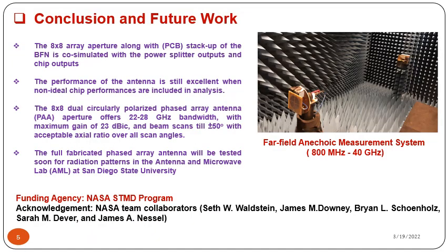So this 8x8 array aperture along with the PCB stack-up of the beamforming network is co-simulated with the power splitter outputs and chip outputs, and we found the performance of the antenna is still excellent when non-ideal chip performance is included in our analysis. The 8x8 antenna aperture along with the beamforming board is fabricated, and the full fabricated phased array antenna will be tested soon for radiation pattern in the Antenna and Microwave Laboratory of San Diego State University.